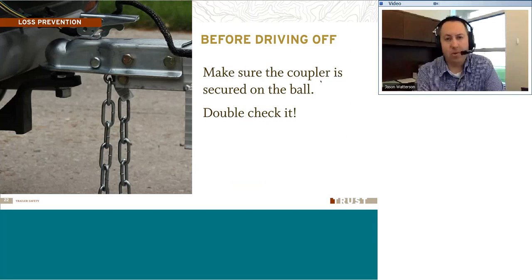And one of the most important things with a trailer is check it out before you drive off. This is something that I like to do when I hook up to a trailer. I'll just double check everything. It takes a little bit of time to get the ball centered under the coupler and to get that lowered down and locked down and connections in place. But it's important that when everything's ready, just do a quick walk around and check it out. Make sure that everything's connected. Check the chains. Make sure it's all good to go, because you don't want to have something come loose or have something flying around as you're going down the road.